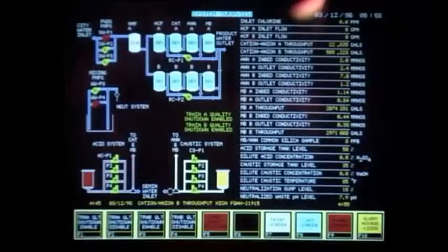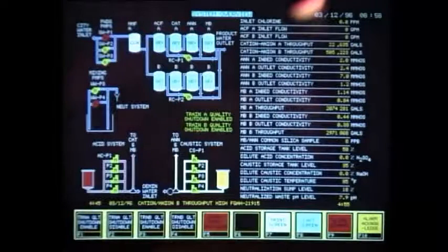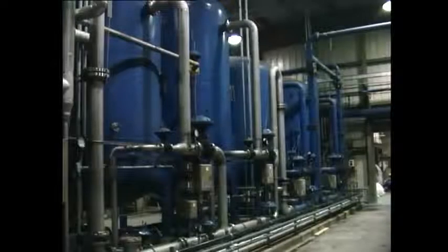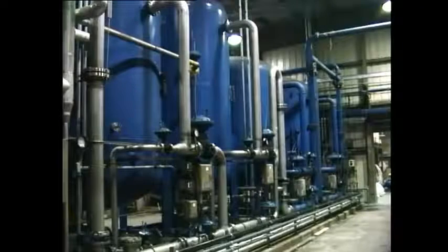In order to achieve this condition, we need particularly high-quality water treatment equipment for producing makeup water. We shall be talking about demineralizers and other water treatment equipment in another module in this program. The problem of silica is so serious that in the event that we cannot reduce the silica content in boiler water, it will be necessary to reduce the operating pressure on the boiler and consequently the power output of the unit.